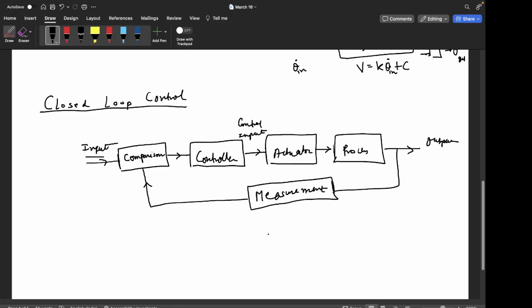So you can think of it as, let's say it's a 2R manipulator, right? This actuator block I am drawing here gives me the joint torques, tau 1 and tau 2. So torque is the input here, right? And in most of the cases there is a joint encoder placed at these joints. Joint encoder is a sensor. There are various kinds of joint encoders, but it will mostly look like a small button kind of thing which is placed on an electronic circuit, right?